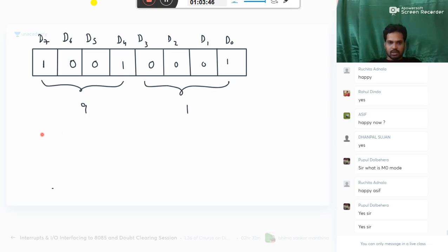Now please listen here. Address bus A7, A6, A5, A4, A3, A2, A1, A0 can be 1 and all zeros. This will give you the address 80.